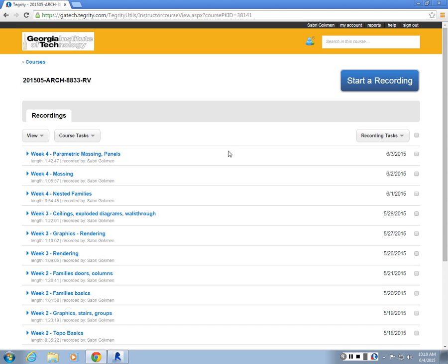Because each tile here is in a distorted 3-dimensional configuration, right? So if this is a NURB surface, you're extracting a tile, you're basically looking at the positioning of those 3 points. So that means in an adaptive component, these 3 points are flexible. They can be in any configuration. So that's why we lock whatever geometry you want to do for the panel to these 3 points, and the placement of those 3 points control the geometry of the panel.